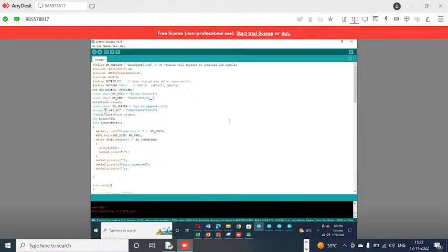So now we are doing the weather project, right? This is about the connections. First we use a library function, ESP8266, which we have to download. Then we have to download the library function of DHT11. We are connecting to the D7 pin. This is all about the Wi-Fi connection. Whatever server you are taking, ThingSpeak. First we have to define whatever cloud platform you are using. I am using thingspeak.com.